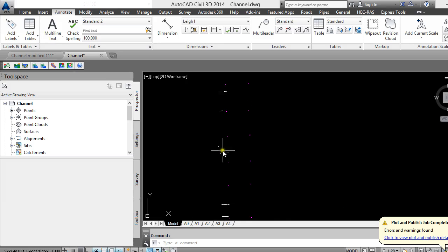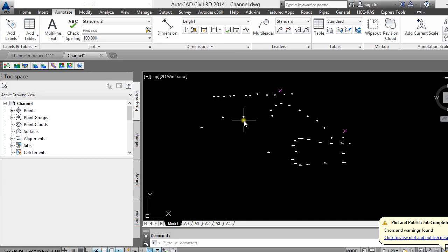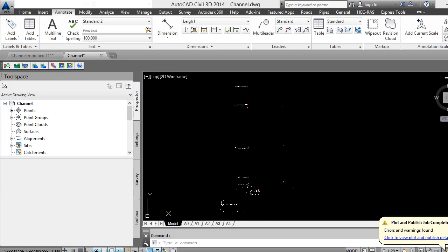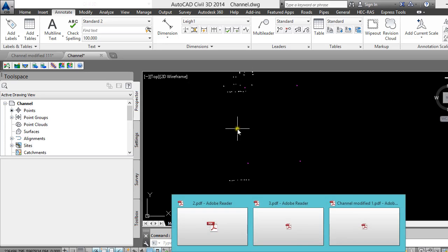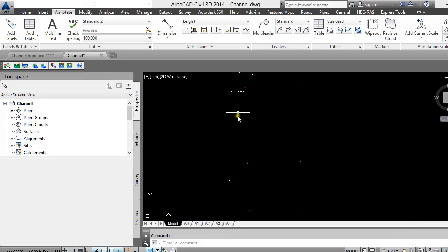So without going more into detailed technical aspects, I'm just gonna highlight the main steps in Civil 3D. Basically, we focus more on a feature line, how we can create the trapezium shape, the one I showed earlier, and how we can measure the earthwork volume. So this is the channel here.